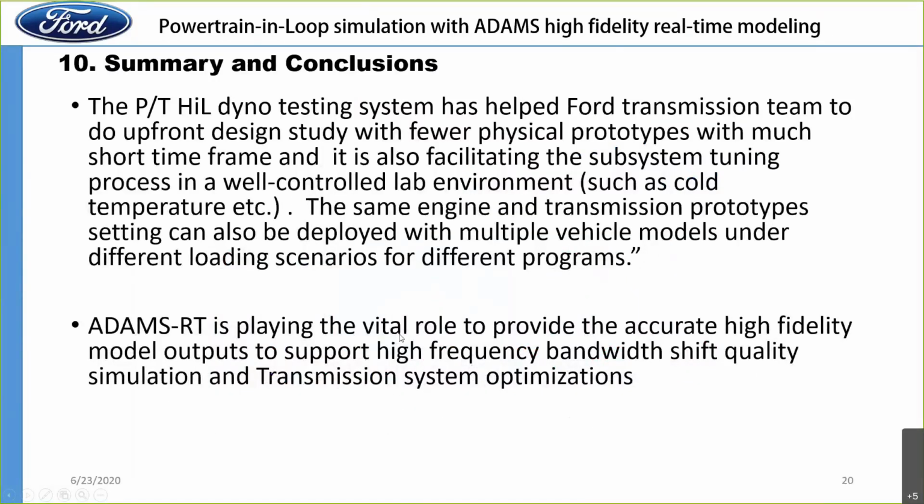Therefore, in conclusion, the powertrain dyno testing system helps the Ford powertrain transmission team to significantly improve efficiency up front. It also facilitates the subsystem tuning process under a well-controlled lab environment, such as cold temperature. We include a cold temperature cooling cell in there, and we can adjust the temperature all the way down to minus 40 degrees.